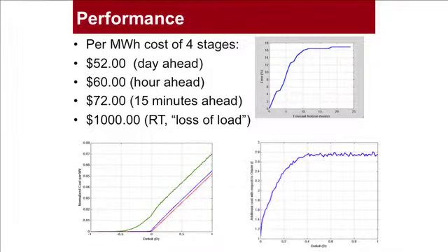What we found out when we did studies for EPRI is that if I had an oracle that told me exactly how much wind I'm going to generate, that's the best performance I'm going to have. And that costs me a certain amount of dollars to get my deficit to 0. On top of that oracle, my additional cost is only about $2.6 per megawatt. That compares to the cost today for integrating wind, which is estimated between $6 and $8 per megawatt. So just some simple control calculations can really help you here.